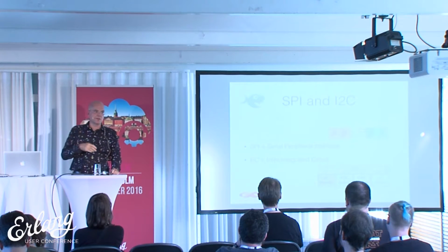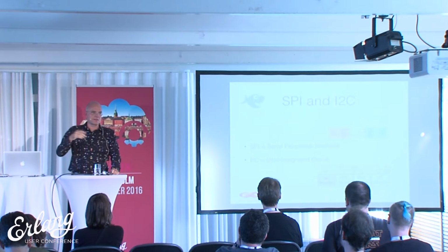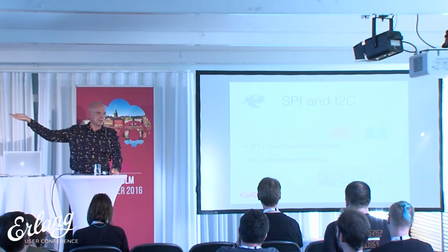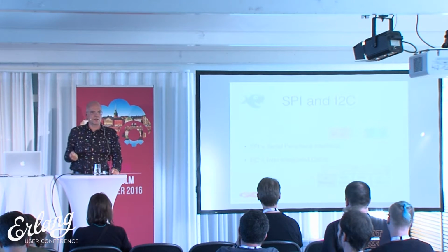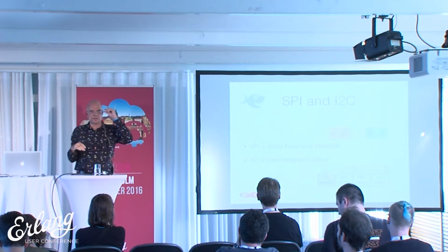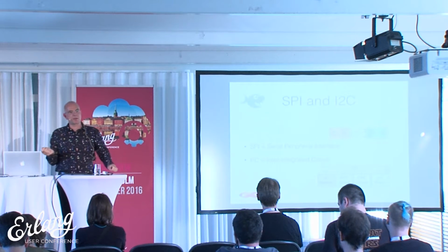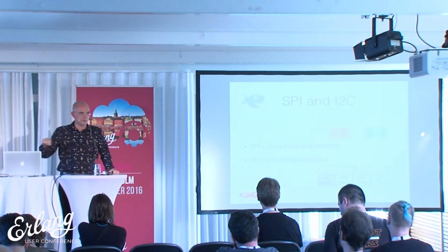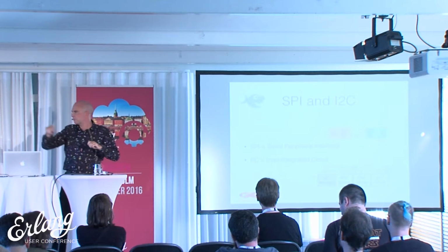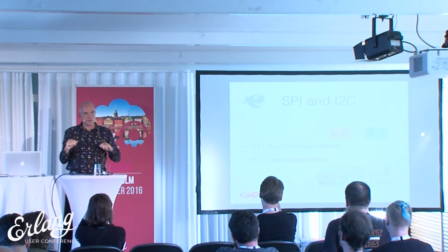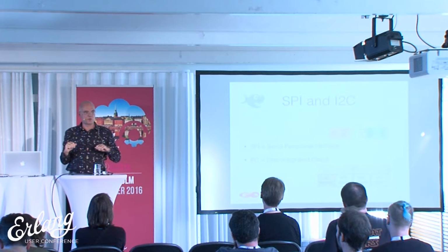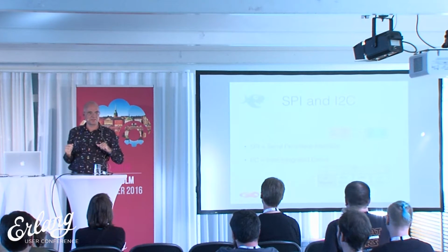And then, if you know the address, you send out one byte, the address. I think it's a one-byte address. You send out the address, and then you send a data packet, and then the chip answers with the answer to the data packet. So you have a little bit more high-level protocol, but only by so much. Then you can talk to many chips, but this is normally used for talking on the same board, not talking to a sensor over there. Some people use it like this, but that's actually abusing it, and it doesn't work too well if there's some noise or something going on.